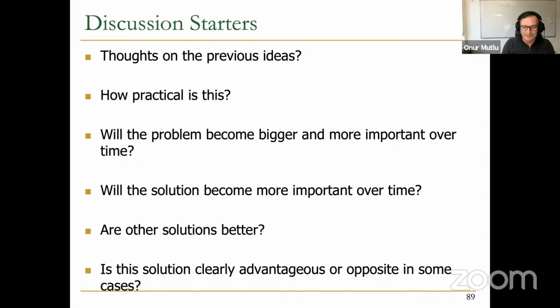But if what you're asking is, can you do fast parallel mode inside a subarray and do it selectively on some bytes? I think you should take a look at our SIMDRAM work, for example. The SIMDRAM work enables that sort of support. But of course, if you operate at a smaller granularity, if you want to modify only a small number of bytes, but you really are copying at the row granularity inside the DRAM, the efficiency is not as high as it could be.